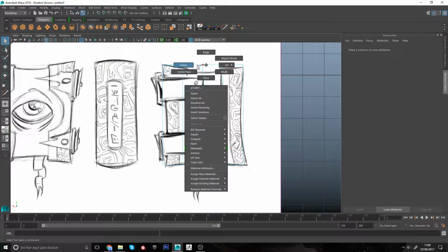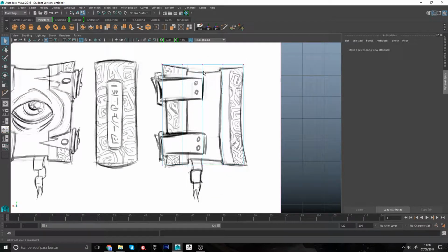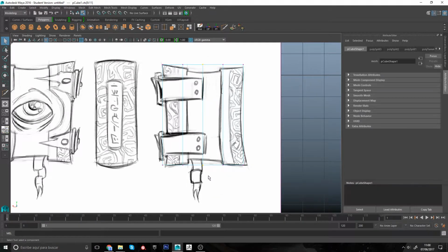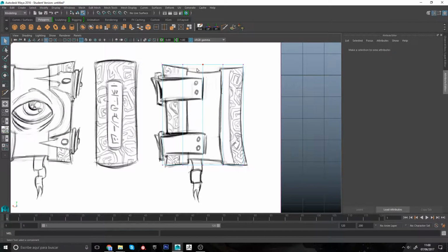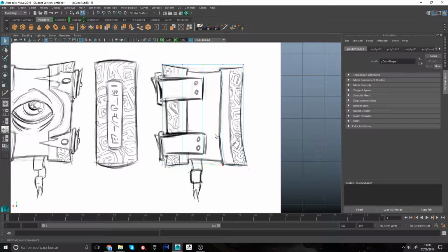If you hold down Shift while doing the loop, we'll get a snap so we can center our edges. The edge will be divided into 10 different units so we can snap or fit it in perfectly, so we can place our loop exactly in the middle. We'll make 3 loops to fit the geometry in with the cuts of our reference.